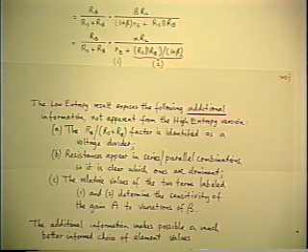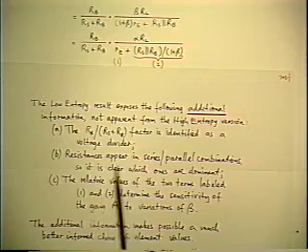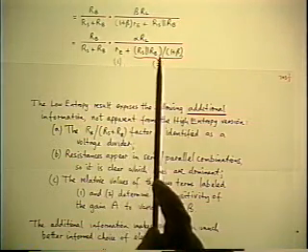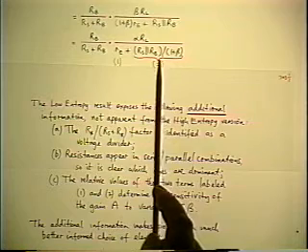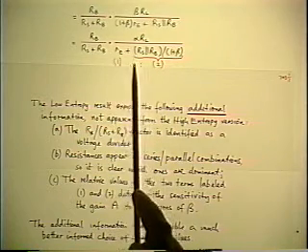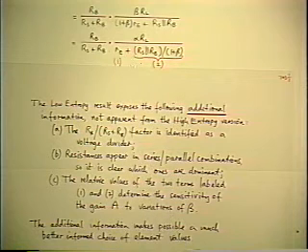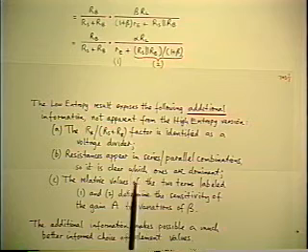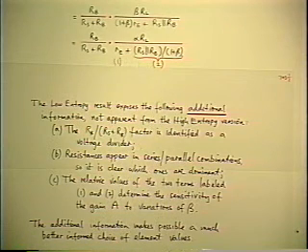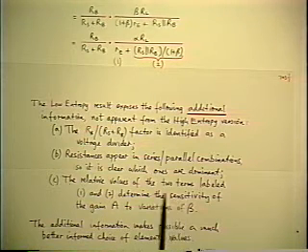So that's useful information. Next thing we notice about the result is we have these series parallel combinations of resistances. That's useful information because we know series combinations are dominated by the biggest one, parallel ones are dominated by the smallest one. So we know what the relative importance is of these various resistances in the answer. That's the one I mentioned in the introduction. But there's still a third one.